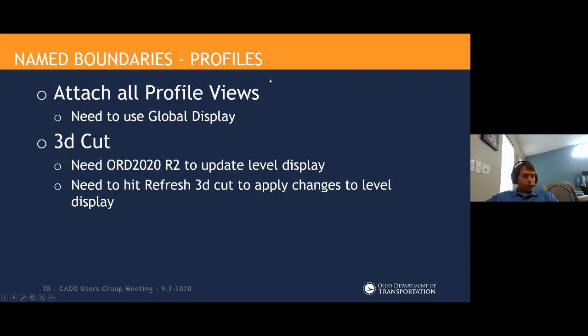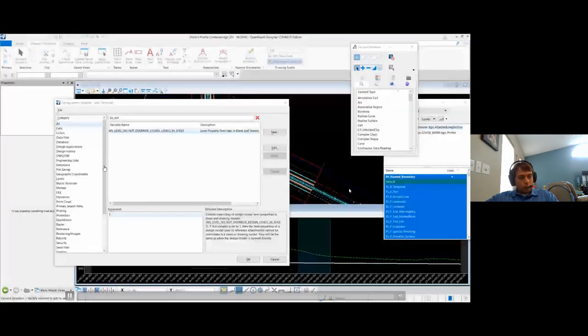Some other things you can do with profiles is you can attach all profile views, which I'll go over in the video, and that controls auto display globally, as well as when you add a 3D cut. But to control level display with that, you need to have 2020 release 2 of ORD, and you need to hit that refresh 3D cut button to actually apply those, which I'll show in the video here.